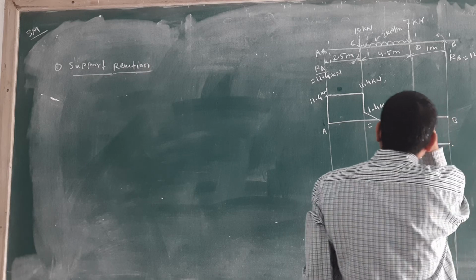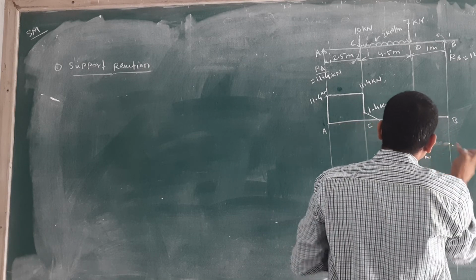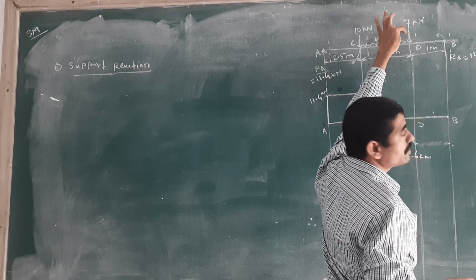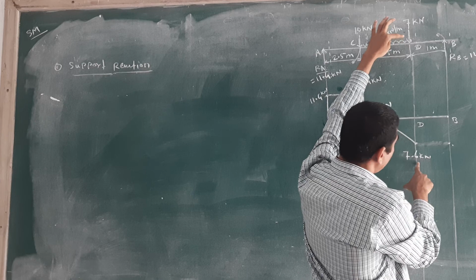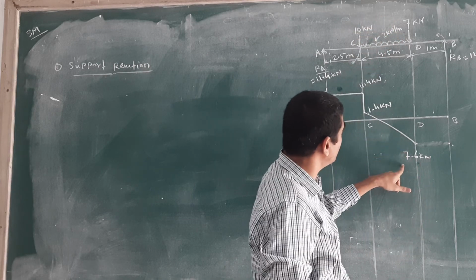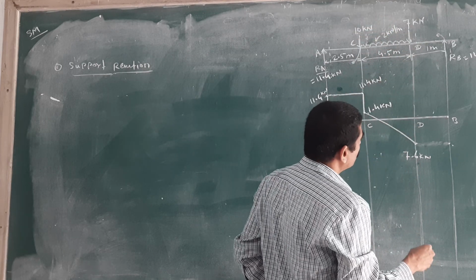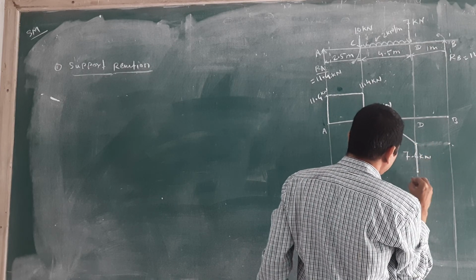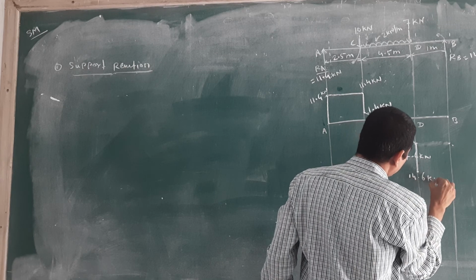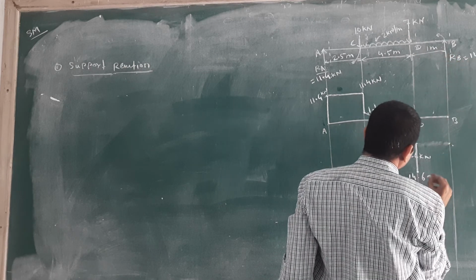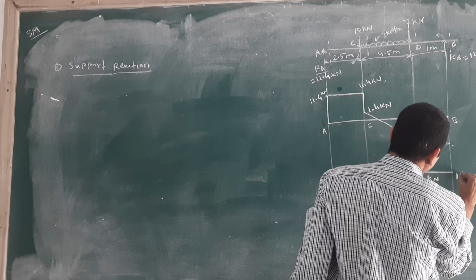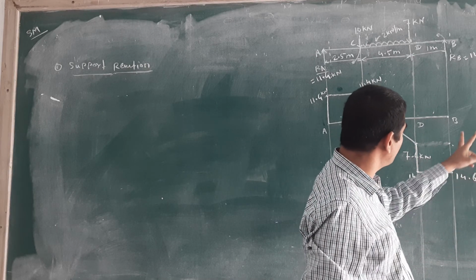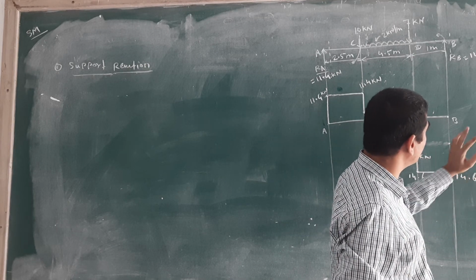Then, sorry, here is one more load in the downward direction, 7 kilonewton. On which point? D point. We already have 7.6 kilonewton, and with the 7 kilonewton load we will get 14.6. Yes, we are coming to the same point. We will get 14.6 kilonewton. There is no load in between D to B, so we will travel in a straight line. Again, you will get the same load. Guys, check that you will get the same load at the B point, on the left side and right side also.